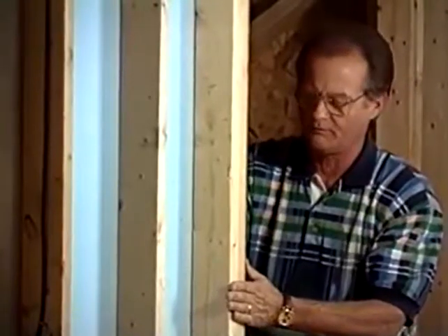Now we can see by putting the insulated sheathing on the back side, we've created a closed cavity which will reduce infiltration, give our insulation a backing when it's placed in the wall, and also reduce the amount of moisture that can migrate into this wall. We're now ready to install insulation in each cavity.